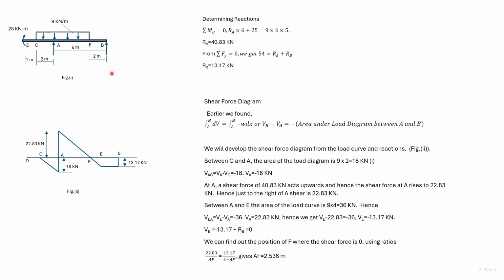For this problem, we can develop the shear force diagram from the loading diagram using the integration method in full. However, because there's a moment acting, we cannot develop the bending moment diagram from the shear force diagram wholly.